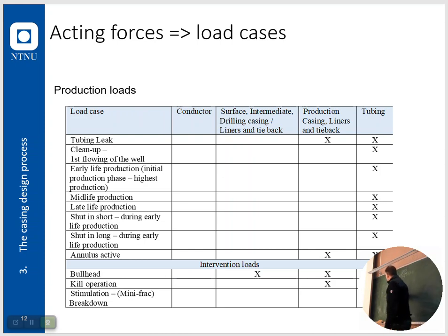Let's say that there's a density of 0.6 SG on 150. That means that you have 1.03 down here. You have 1.03 plus this pressure on top. So the pressure curve for this casing will start at 150 bar here, and then the curve for 1.03 goes down like this. Okay, and of course it stops at the packer,